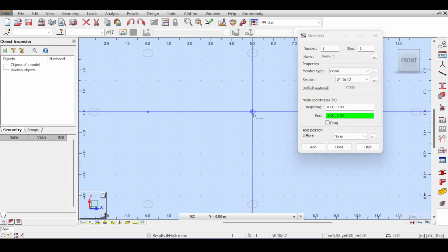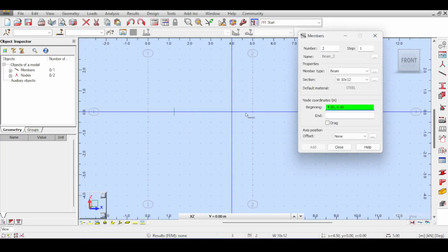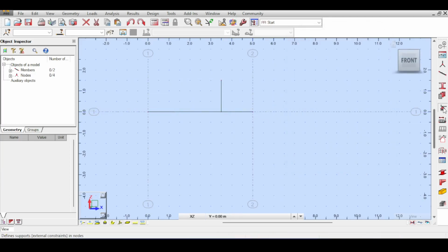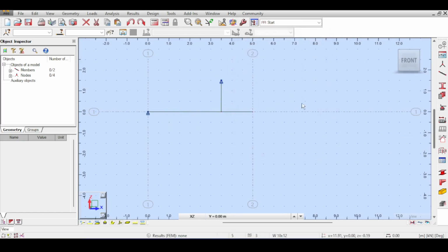With that being said, I'm just going to make a simple beam like this. And this time I will make a beam that is connected to, I don't know, a bar like this. This beam alone, if it's on a pin, well, this would be unstable, obviously. But if I have two pins now, this beam will be stable, meaning if you just run the analysis, you would have a simply supported beam, which makes sense. I'm not going to release anything. My goal is not yet to release. I just want to see that it's stable. So I will make a pushover analysis on this one, pushing it down.